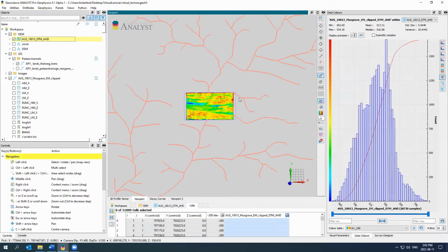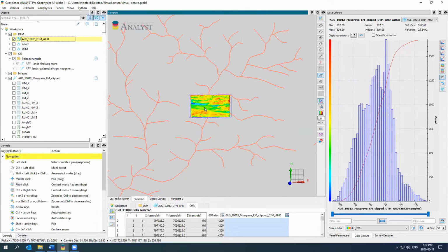What we're looking at right now is the MAG data. So we're looking at the TMI, and we have this bedrock stratigraphy that strikes mostly east-west. Although some of the paleo channels are defined and controlled by this bedrock, the main ones, as you can see, are north-south, and so they cross-cut the bedrock strike.